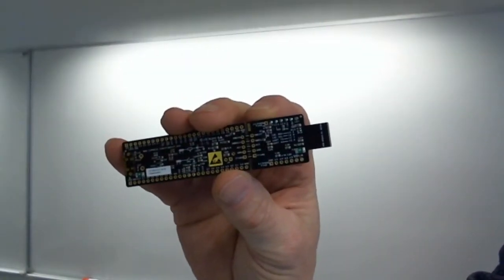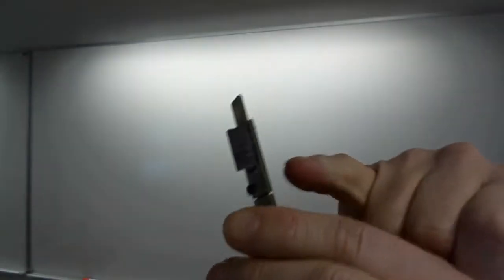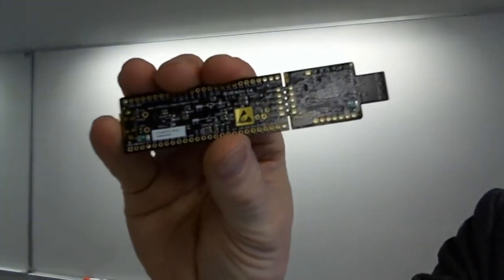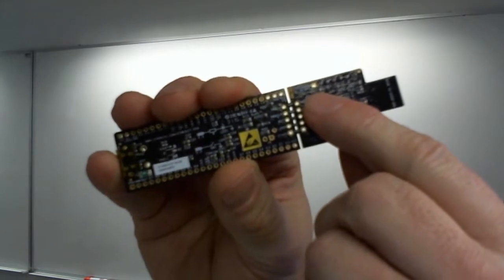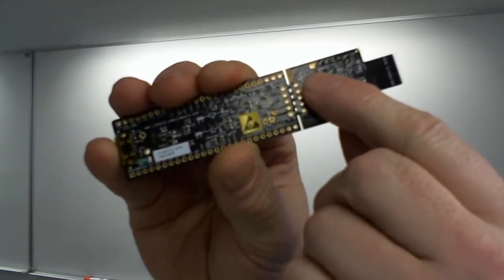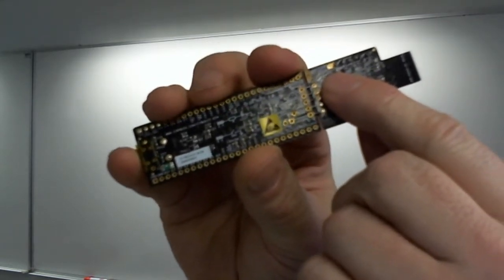And by the way, it doesn't work without a common ground. So you also need to have a wire from common ground, which should be on the other corner here. Please observe that there's also one pin actually open right there. Oops, where? There, it's intentionally left open. That would be the power pin. So if you make this kind of boards yourself, you might actually consider leaving that kind of power pin also unattached. Otherwise, you'll be shorting ground with power. Not a good idea.